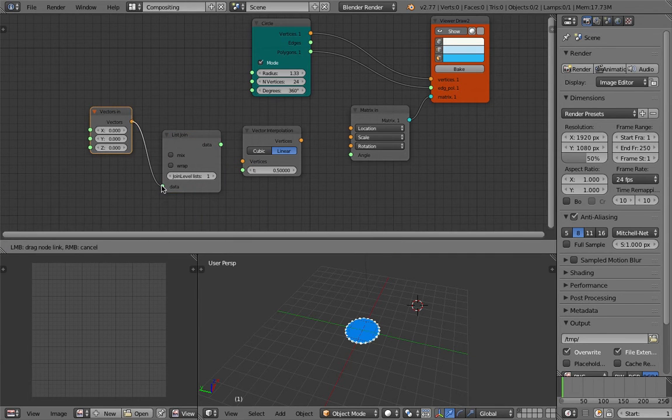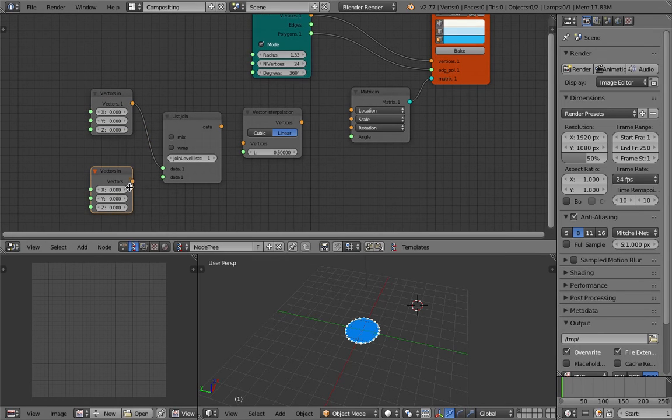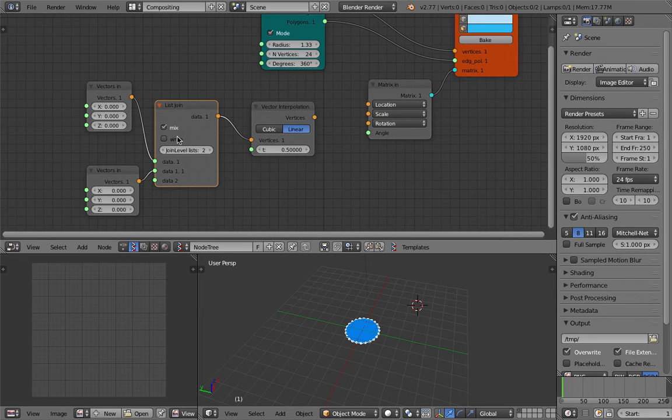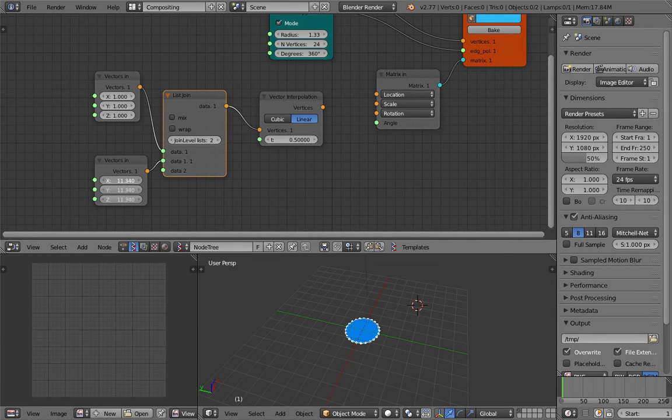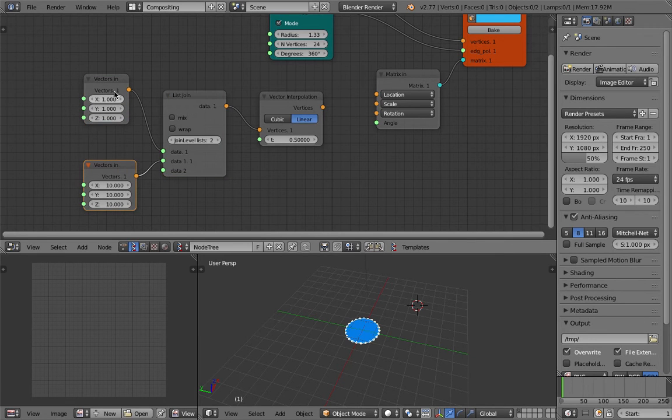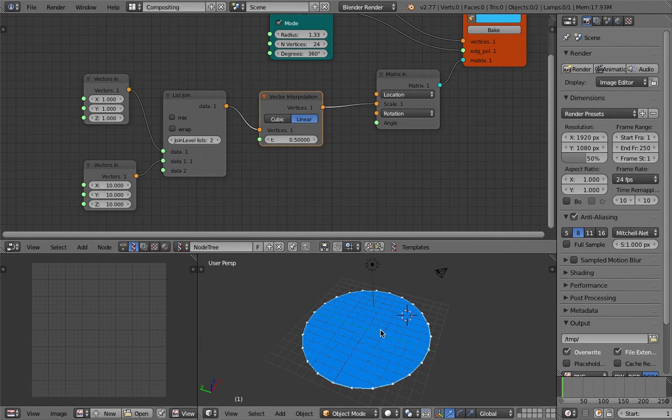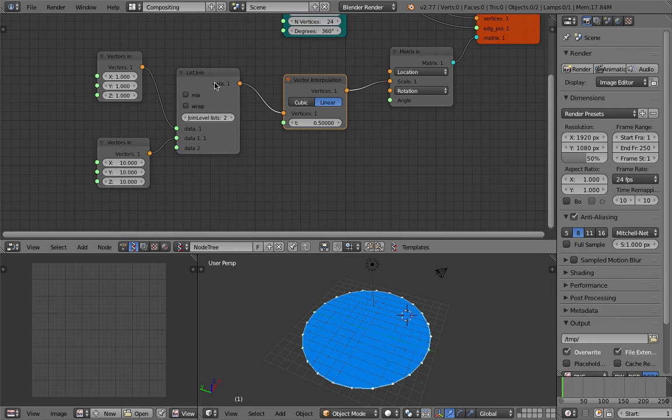Yeah, I got confused just now a little bit because I was thinking about Animation Nodes, and then we're using Sverchok. Let's try this anyway. So scale requires a vector, so it's vector 0 1 1 1, scale 1 1 1 to 10 10 10, and then see the result. And okay, seems to be working.